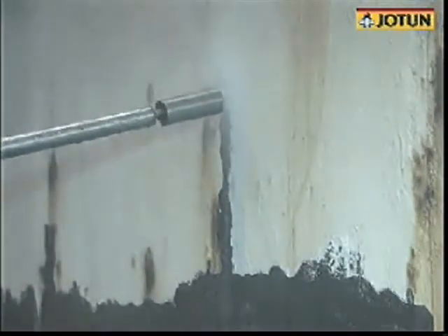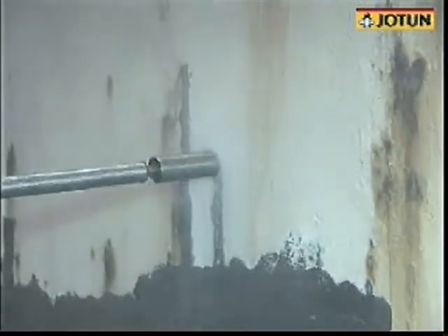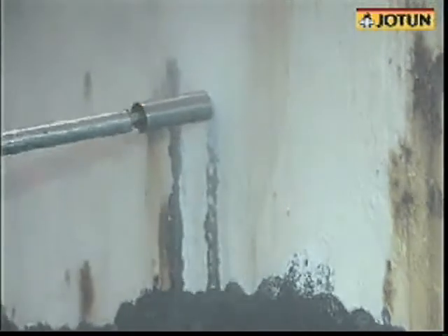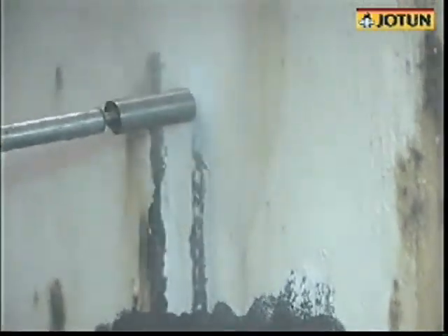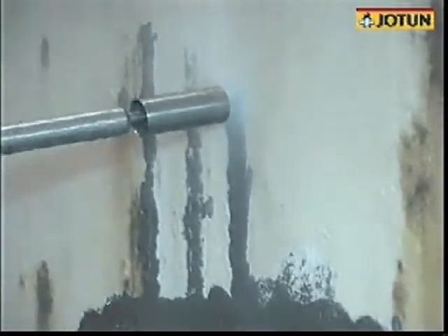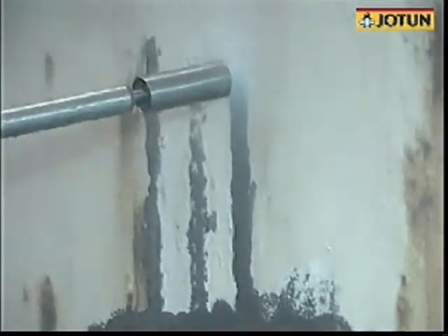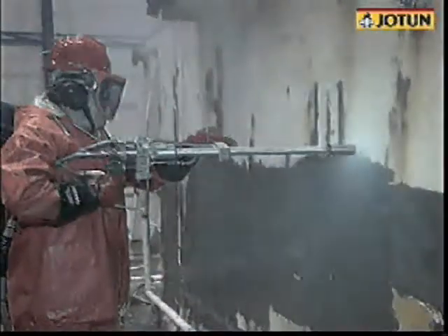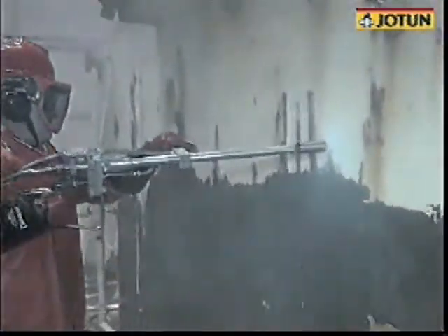Here, 4 different pressure levels are evaluated with respect to cleanliness and production rate. It's evident that to achieve a good result, the pressures should be at least 2000 bar. If lower pressures are used, 750 and 1000 bar, you need to wash slowly or repeatedly, and still the cleaning may be insufficient and the paint may barely be removed.